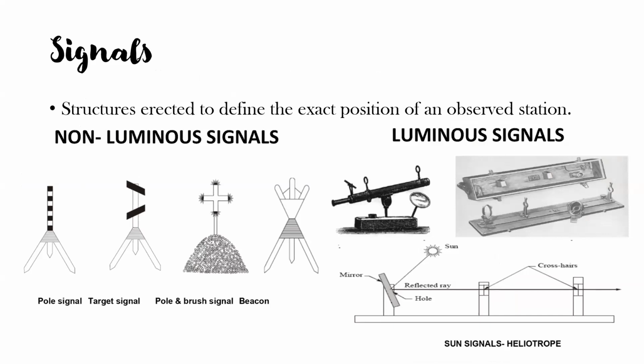Why do you have to erect it? So that from any point, the exact location of the triangulation station is clearly visible. Now, these signals are classified into non-luminous signals and luminous signals.